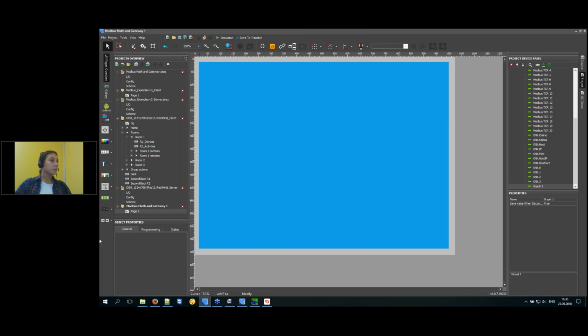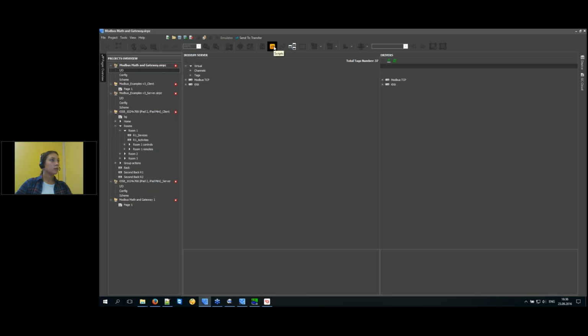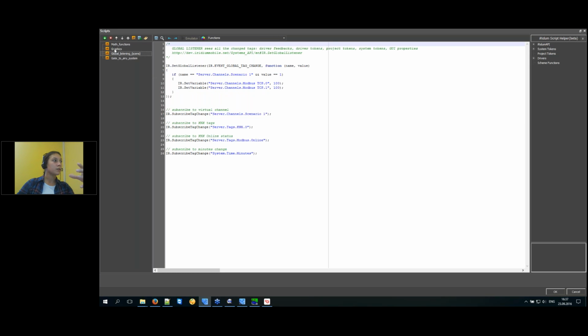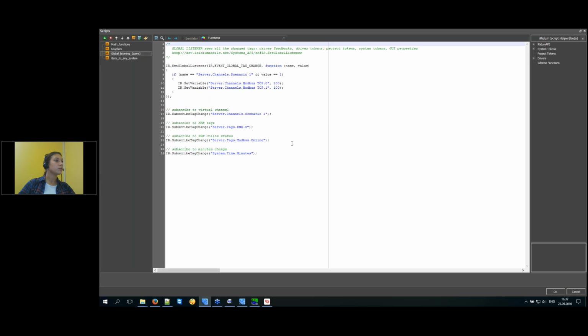Okay, and the next step. The next capability of Iridium server is that you can transfer the data between different automation systems. You can easily transfer the data without some physical gateway. For example, you are able to send the data from KNX to Modbus with a physical gateway, but it could be too expensive and it makes some limits of usage, so maybe it will be easy to use Iridium server for data gateway.